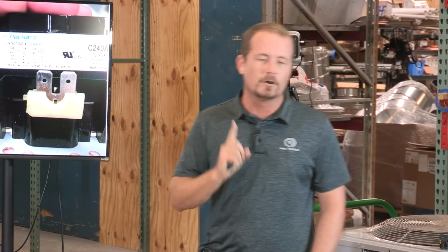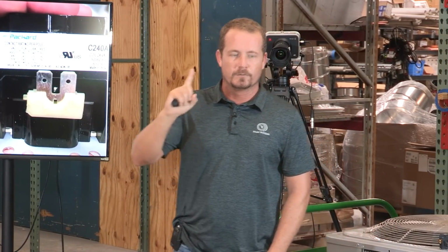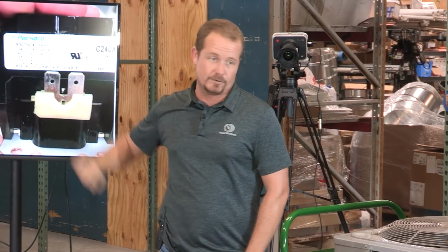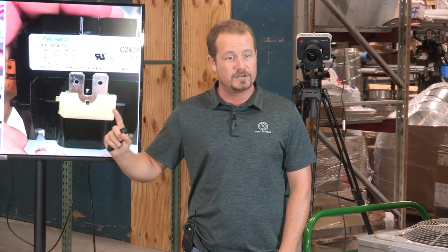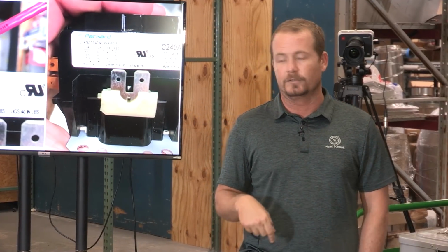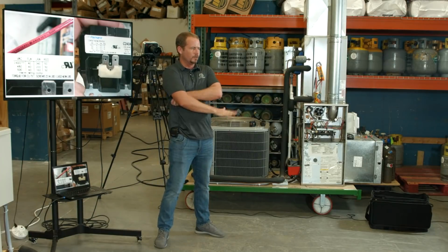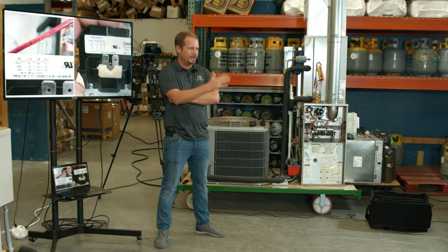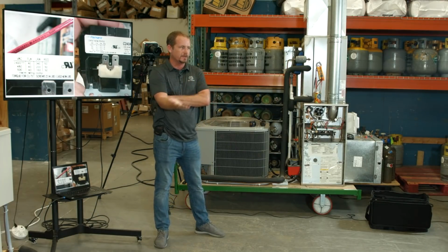Other than that, bigger wire does serve to reduce voltage drop. Higher insulation rating does not. Higher insulation rating keeps it from melting, but the voltage drop is going to remain the same because the internal conductor is the same either way. So if you're trying to beat voltage drop, then you've got to put in bigger wire. But very rarely are we trying to beat voltage drop. So does that make sense on the voltage drop versus the insulation side? They are different, and a lot of people get those confused.